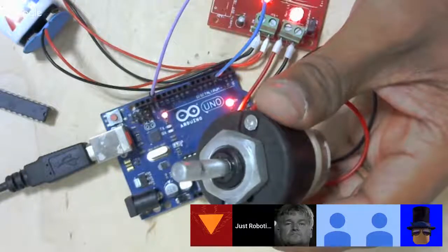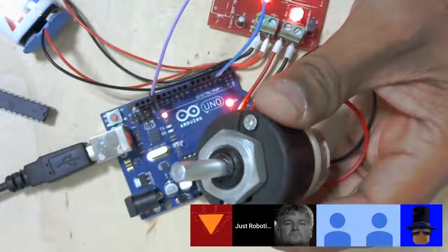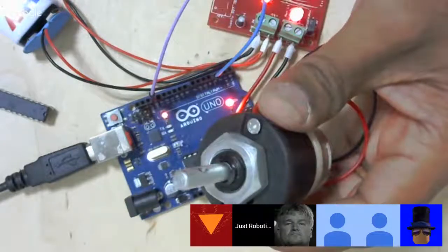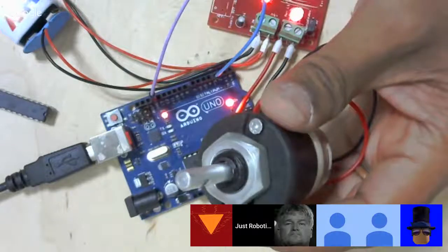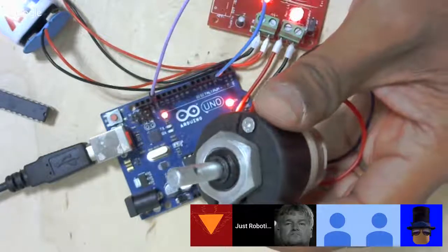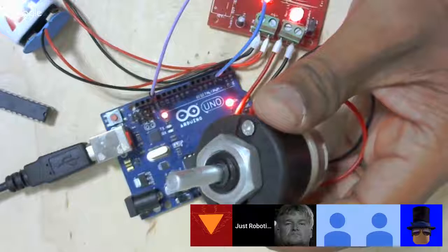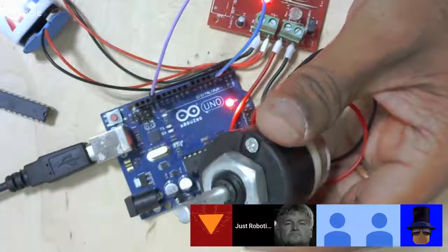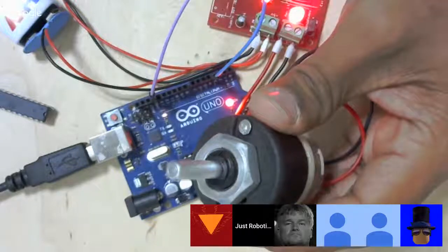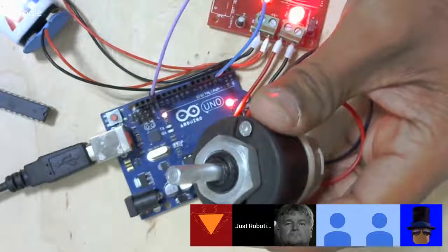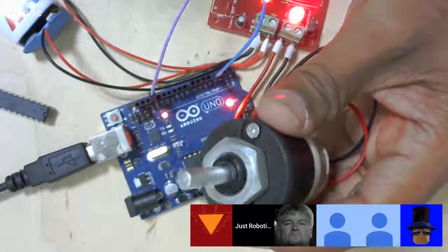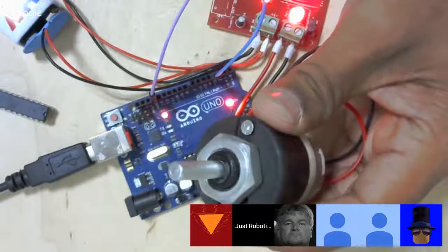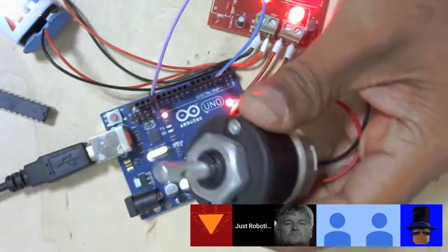Okay, I would want you to try this out. Try this out for yourself and see how this is going. And then probably I will bring it up to 255. High, full speed. So this is speed variation, and this is what analog write is, and this is what we will start using in our program to control the speed of our robot.